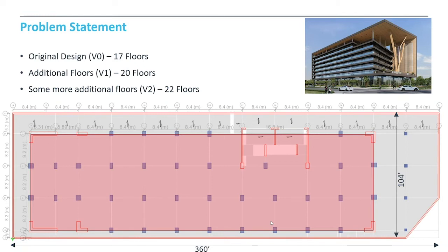I think the car parking level was just above the ground level. But since the construction had not reached that level, the structural group took care of the design of that particular level, and only the additional force due to that stack parking and extra car load was passed to us, and then we used those forces in the column strengthening below.